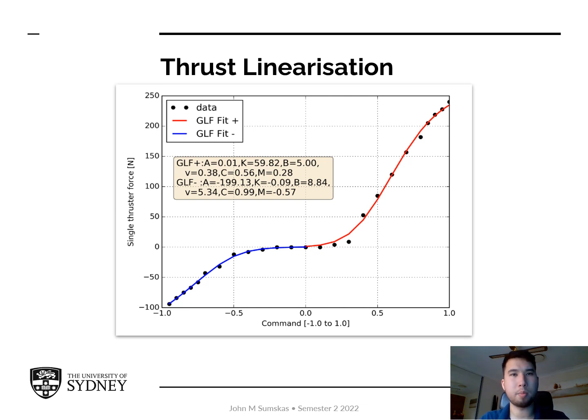Forces generated from a motor are not proportional to the corresponding motor command. Thrust curves provided by the simulation were used to calculate the corresponding motor command for a desired force. For different thrusters outside of simulation, a bollard pull test can be used to determine these thrust curves.